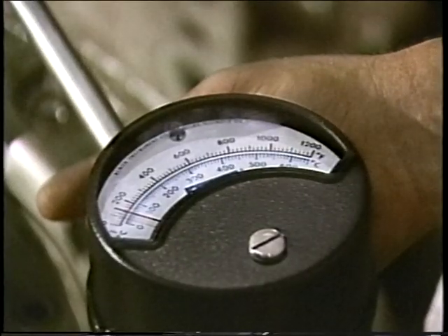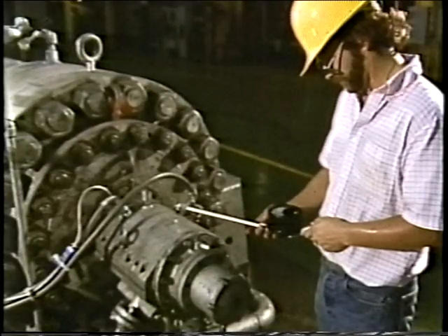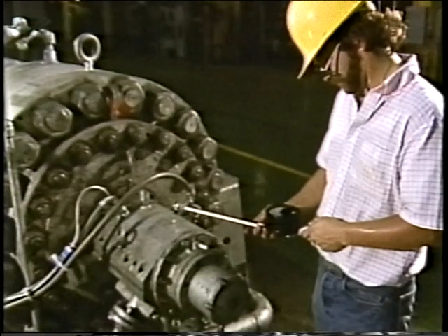Other situations, such as environmental conditions, should also be checked before vibration monitoring takes place. Since extreme changes in temperature can affect vibration, temperatures should be matched as closely as possible to the conditions that were present when the baseline data was collected. It's important to record the conditions that exist when data is collected so that they can be matched for future readings. By matching these conditions, the information collected will be more accurate.